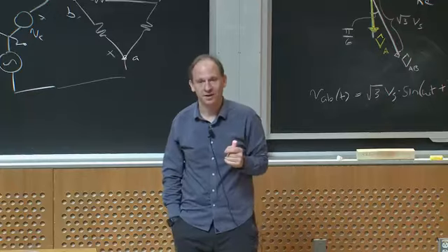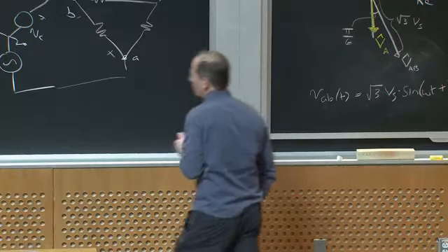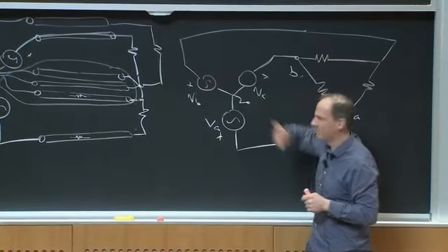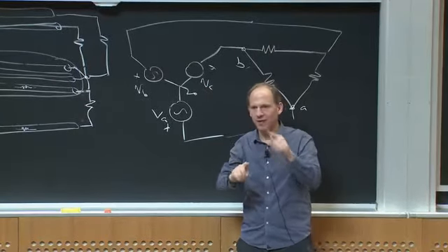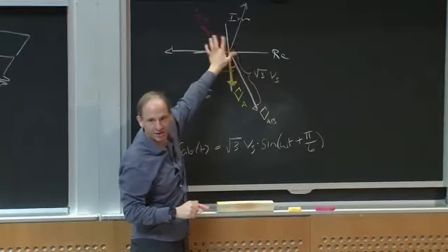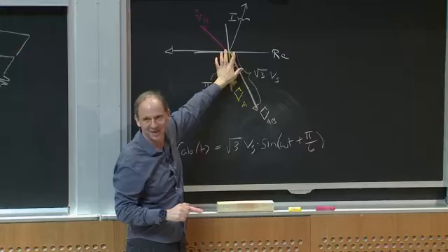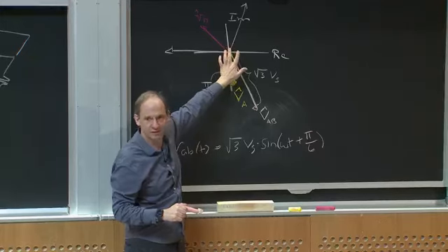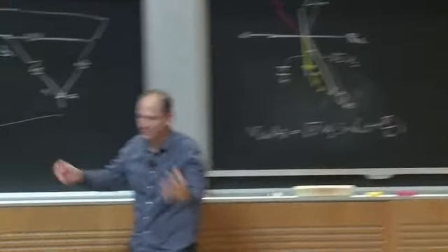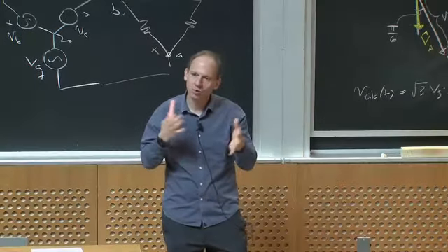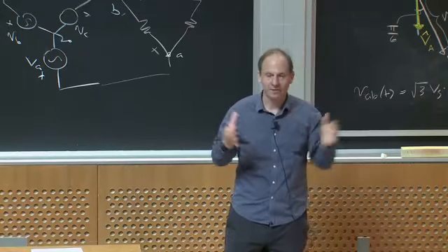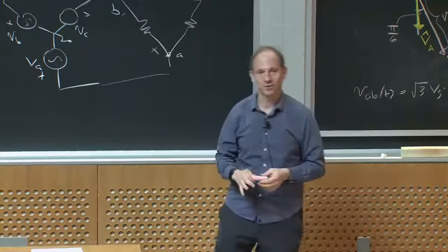But here's the other piece of it. By adding up, I could take transformers. If I had this three-phase set, I could take a piece of this voltage, a piece of this voltage, and a piece of this voltage. If I do that in a balanced way, I can actually create three-phase sets with any arbitrary phase shift that I want. And that turns out to be handy for some kinds of converters you might want to build, because we can do things like we talked about, harmonic cancellation or ripple cancellation with interleaving. I have a natural way to generate phase-shifted sets of signals if I have a balanced three-phase set, and I can generate other balanced three-phase sets.